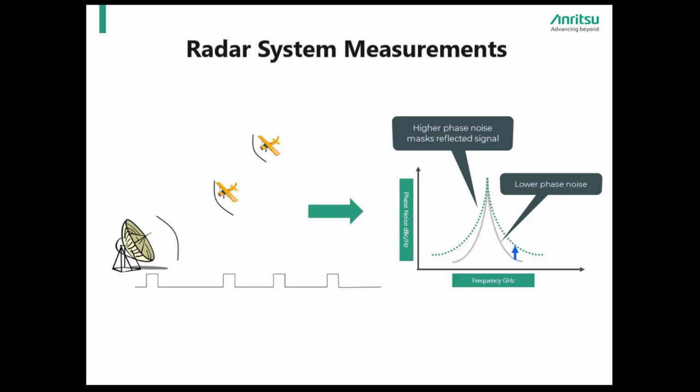You may also notice that some kilohertz down from the signal, there is a frequency shifted and attenuated signal, which is the reflected signal from the radar target. The frequency shift is a result of Doppler shifting, and the attenuation is also a natural phenomenon of free air attenuation. It should be noted that the return signal can be very low in signal strength and almost unnoticeable if